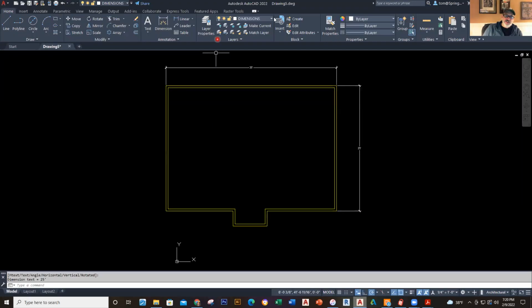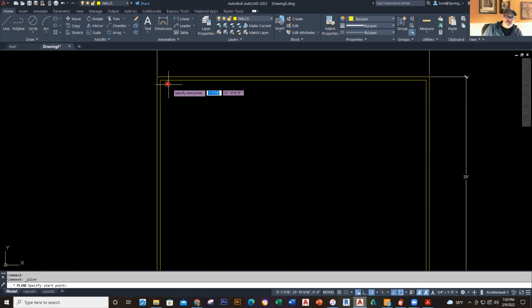So when you're doing the line command, we are going to be using a tool in AutoCAD that's the extension line. Okay, so I can make a polyline or a line out of this one. But if I touch it right here, and if I pull it down, you'll notice it's tracking. I didn't click. There's a green plus sign and it's tracking. You notice my hands are off of it. I need to tell how far away from that wall it is.